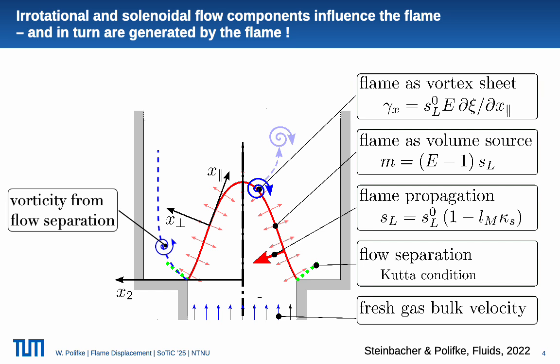In particular, Thomas Steinbacher built a dynamic model of a flame as a combination of several ingredients. First he had a model for the flow as a sum of irrotational and rotational components. So he did not simply impose a presumed functional form of the velocity perturbation, but tried to model this with, on the one hand, potential flow models, and secondly, with velocity resulting from vorticity.